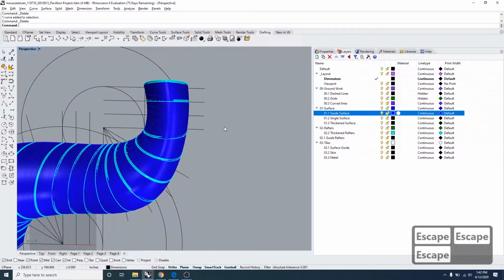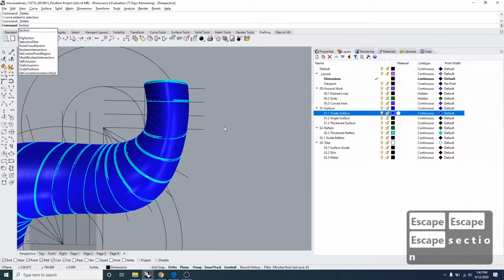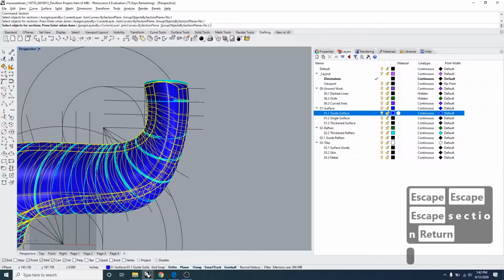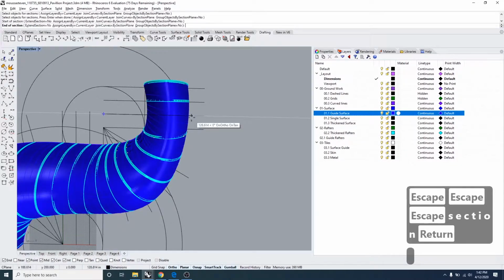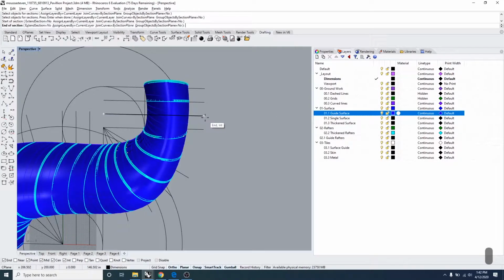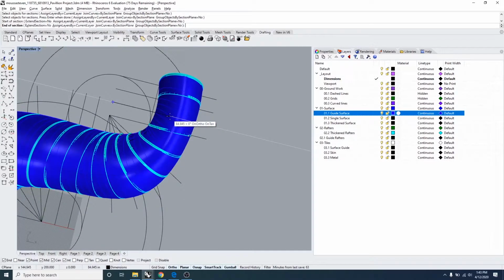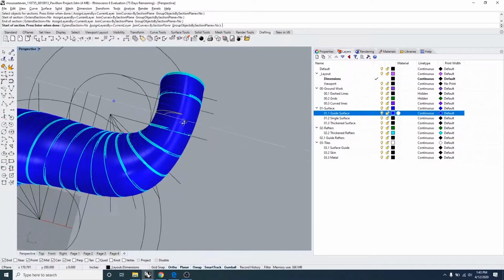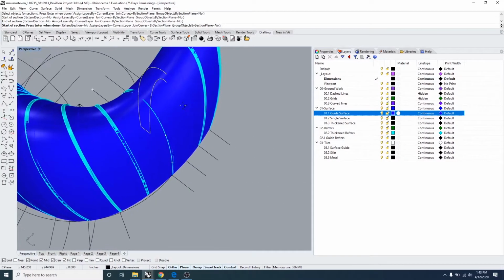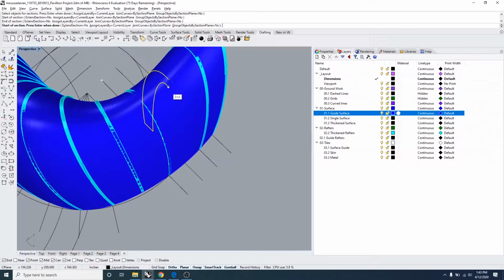And then I'm going to make a section again. So I'm going to run the command again, section. Select my object. Now the issue was because we didn't pick a point that was the furthest away of the object. So I'm just going to pick a point that is somewhere here so you guys can see why that's happening. Now notice that it's a big opening there, and that's because I ended my point perpendicular to this opening somewhere here. So this is happening because we don't go beyond the object.